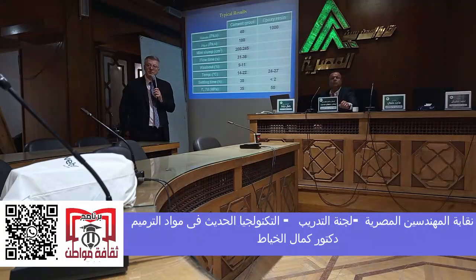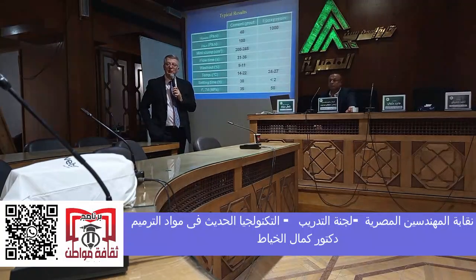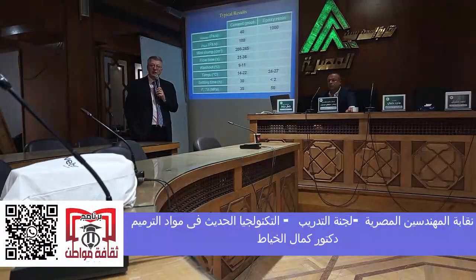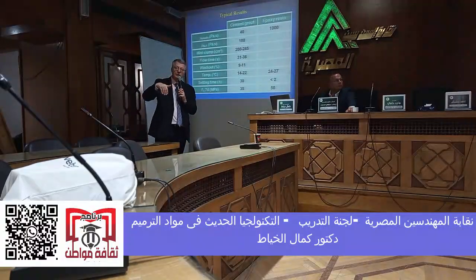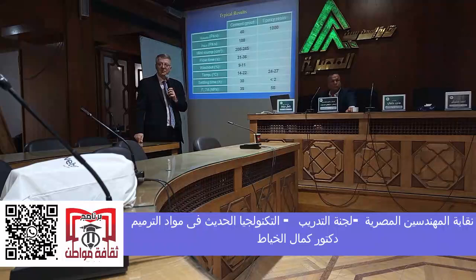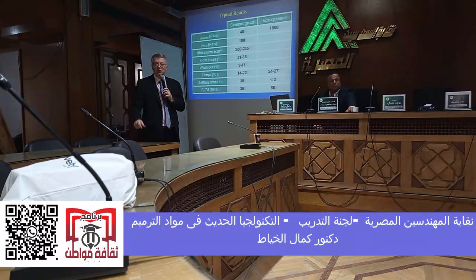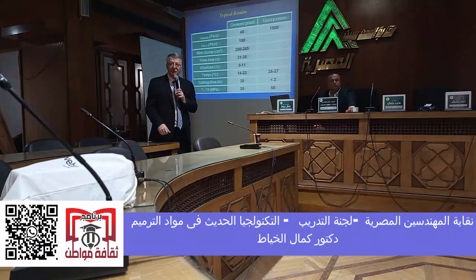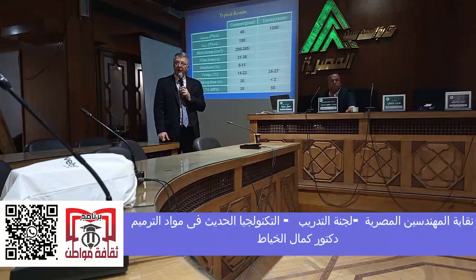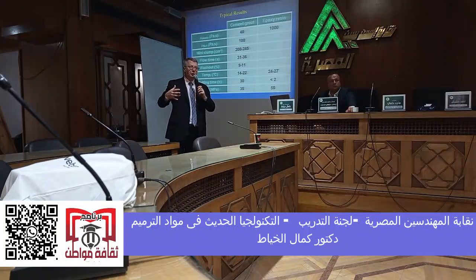What about inside? It's probably not cracked, it's outside. Cracking usually in mass concrete is on the outside. In the first picture we see that it is like shrinkage cracks. Yeah, those are thermal shrinkage. They are shrinkage cracks, but also thermal shrinkage because they cast it as mass concrete, one block, and it cooled off too quickly. They did not control the gradient of temperature, and it cracked on the outside.